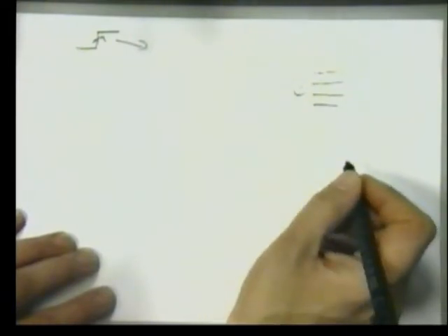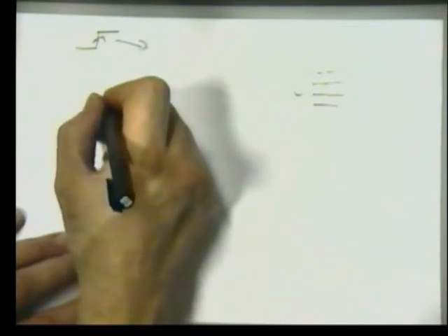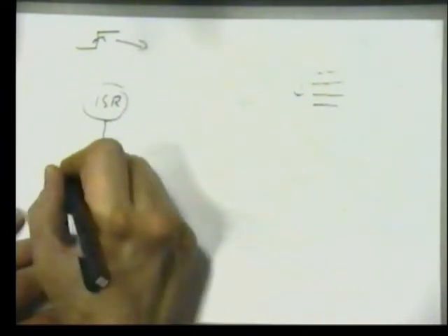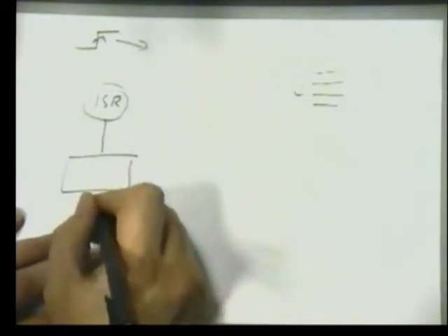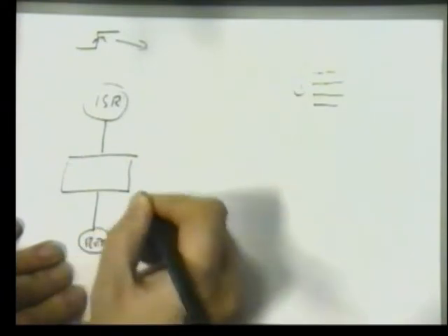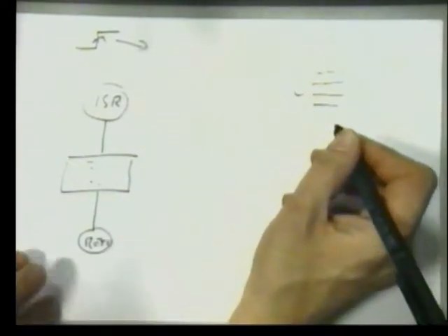What have we got to do?" Well, if this is our interrupt service routine, we have to somehow get to it, execute that code, and get back to where we were in a totally non-destructive manner. Our background process must never know this occurred. How is it going to do that?